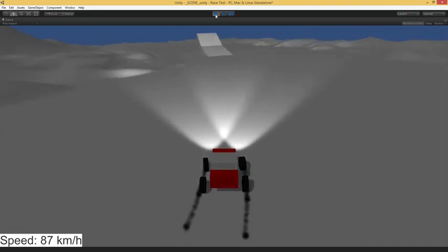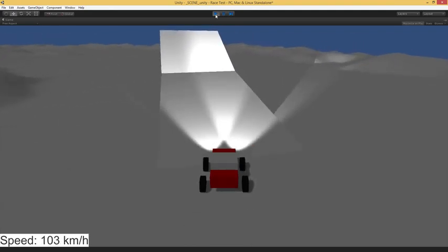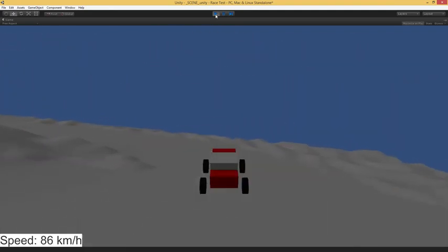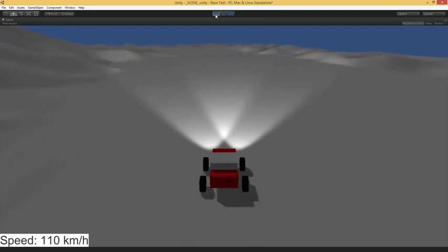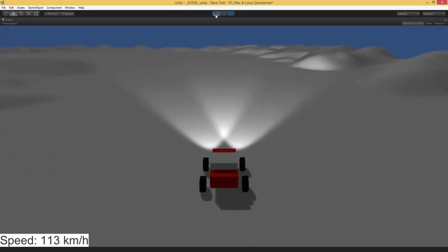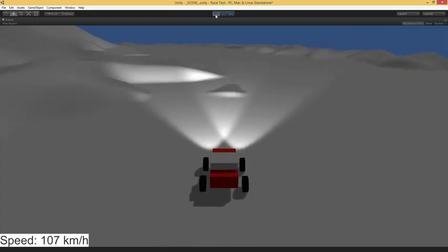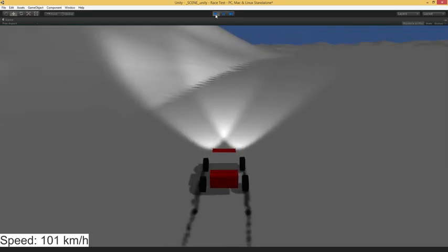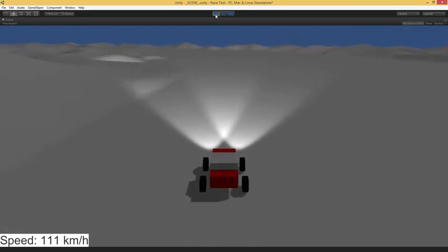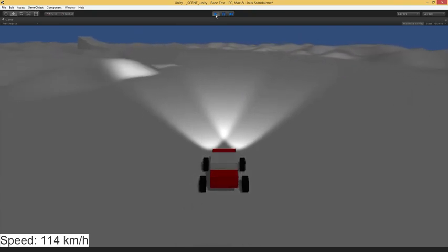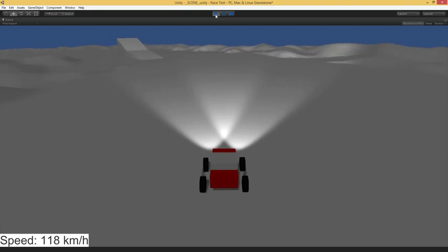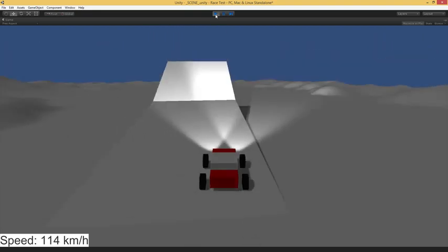And one of the things that people in Unity found out when they tried to make these car simulators is, first of all, the built-in physics system is not great at really simulating a car in terms of tire physics and things like that, which are a relatively complex kind of thing. Just for reasonable collision and rolling physics, you probably have to set the physics engine to such a high tick rate for accuracy that your CPU would explode.